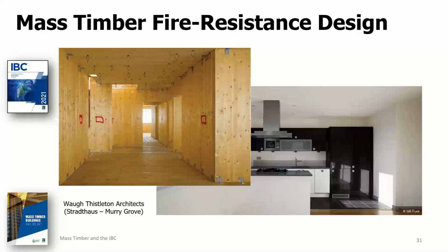Now in type 4C, there is no requirement for any of the fire resistance rating to come from non-combustible protection. In this case, if the designer chooses not to use any gypsum, any non-combustible protection, he or she would need to design the CLT itself to provide the full 2 hours of fire resistance. And I wanted to point out that if this option is taken in the design of it, this may necessitate the use of a thicker CLT in order to achieve the required fire resistance rating without any non-combustible protection.